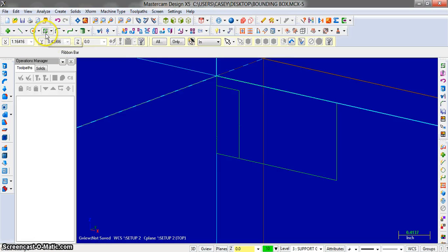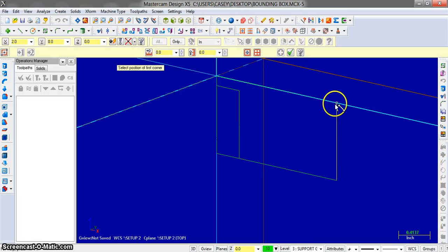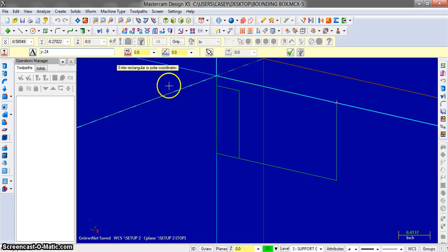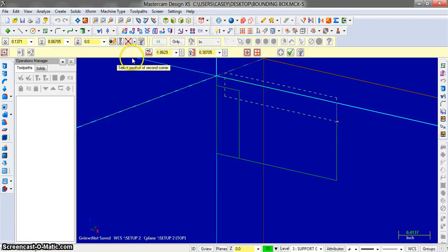Now let's do another rectangle, which you have to first click Create Rectangle. You have to do a shift click right here so we can get the delta command, which you have right here, Y minus 0.24, and it'll just make your point go down 0.24 instead of making a line. And there you have it. And your dimensions for this rectangle are going to be -0.25 in length and then -0.27 in height.